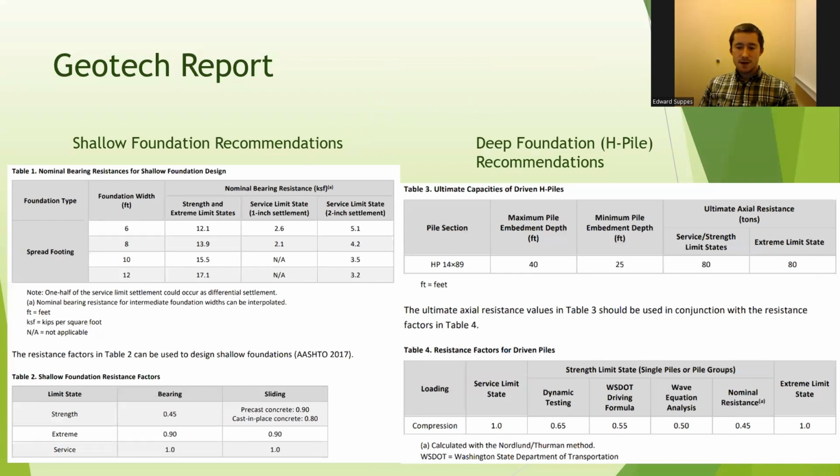The marine sedimentary rock has good bearing properties that are ideal for a shallow foundation and is the recommended alternative presented. Deep foundations are possible, but point bearing capacity was ignored due to the presence of coal in the rock. The following design parameters were given for resistance and bearing design that you see in the tables.